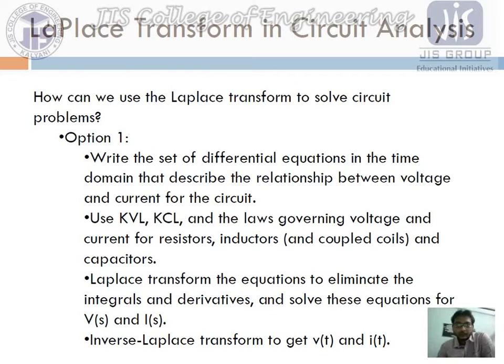So whenever we are going to solve these types of electrical circuits by using Laplace transformation, what are the steps, or how can we do that? There are two different options. First we consider option one, that is, write the set of differential equations in the time domain that describe the relationship between voltage and current for the circuit. So first of all we write the equation in the time domain.